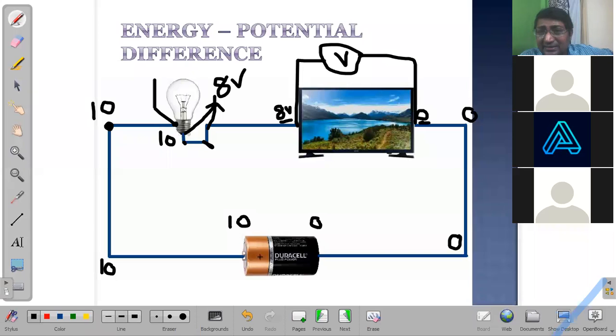And did I connect that voltmeter in series or parallel? Please observe the sketch on the television. Parallel. Yes, that voltmeter is connected in parallel, guys. Why does it need to be connected in parallel? It's very simple, because you're trying to measure the energy difference between these 2 points. If you want to find the difference between these 2 points, it needs to be connected at those 2 points, and such a connection is called a parallel connection.